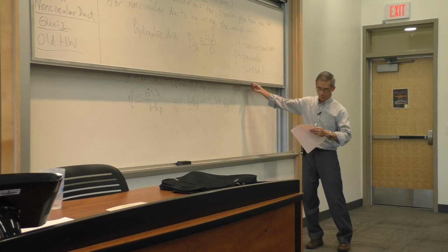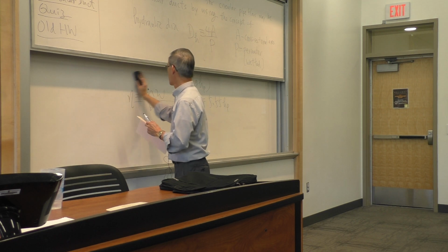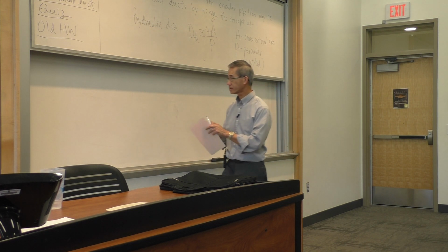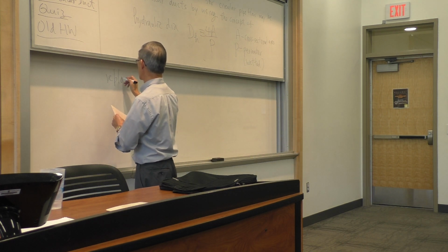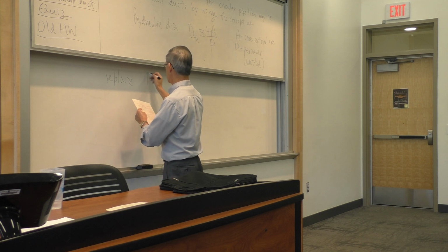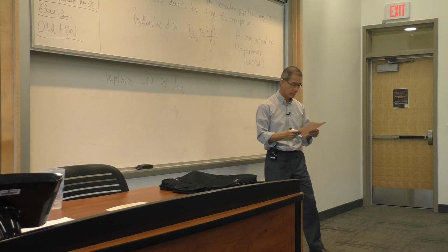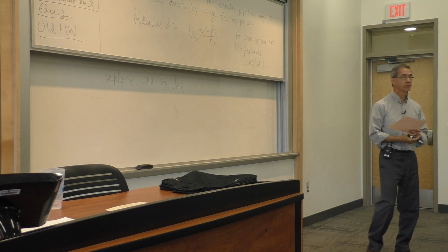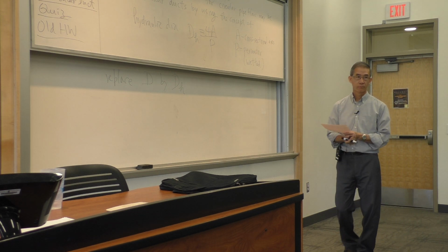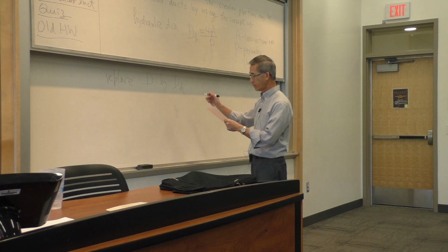So with this definition of so-called hydraulic diameter, now I can use all my same concepts of the Moody diagram by simply doing one task, which is I will replace what I have for circular diameter D with the new concept of a hydraulic diameter. And all the equations I used before will hold. So the Reynolds number, etc., will be calculated based on this new concept.